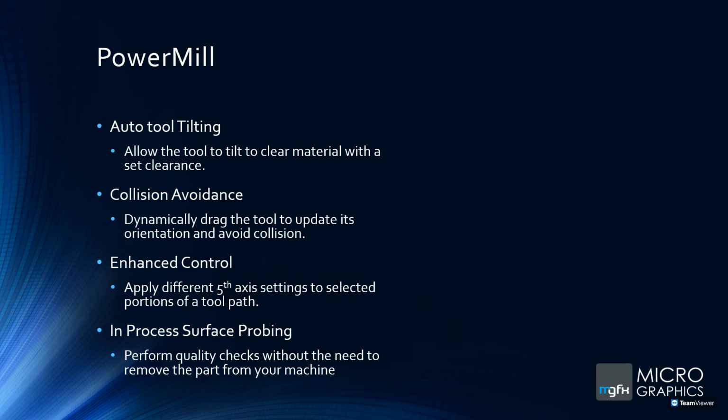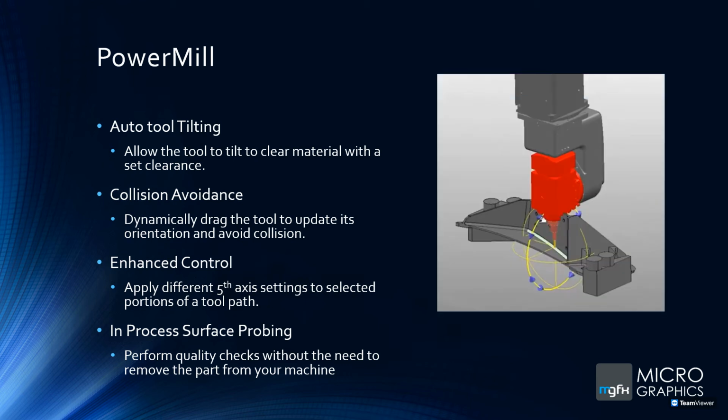So when you enable the axis tilting, you're also able to set the material clearance for the tool holder and assembly to avoid any collisions.